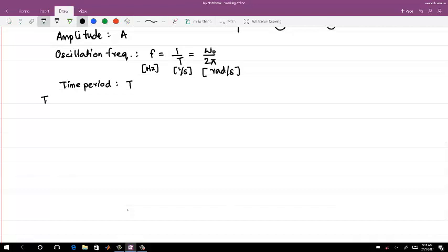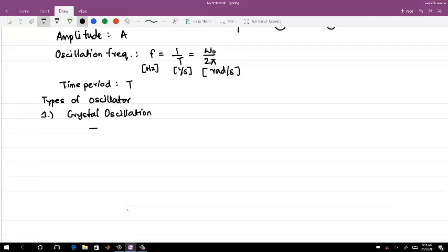So these are just the general characteristics, and I think every one of you knows about it. There are different types of oscillators, and you know that the oscillator is the main block of the PLL because it generates the source sinusoidal signal. Types of oscillator: there are three main categories. The first one is the crystal oscillator. Okay. Can anyone tell the different properties of a crystal oscillator? It is like the one present in your watch, or one crystal which is present as a reference source in all the synchronous systems.